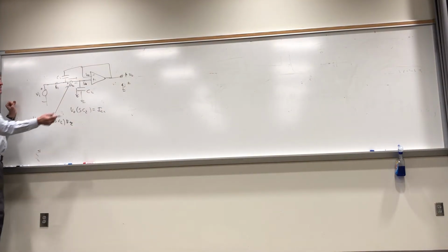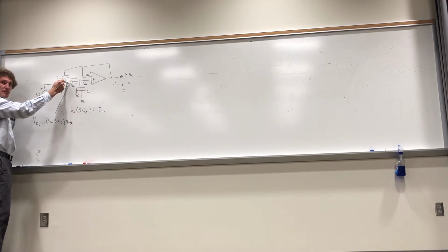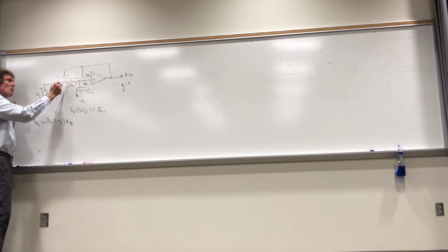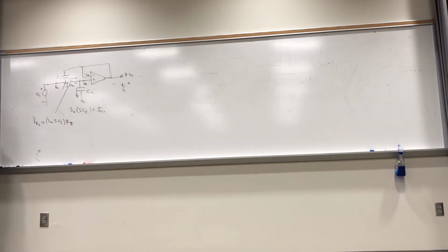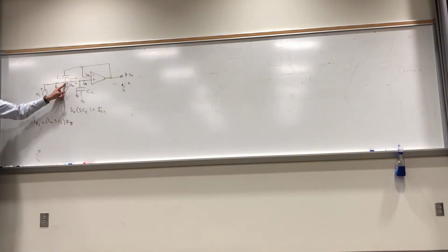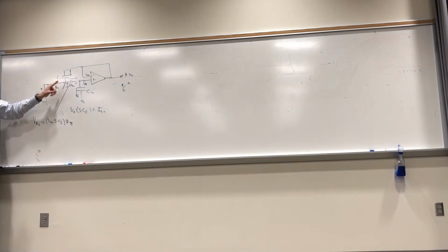Now, once you have that voltage as well as that current, right? You got that current right here. You got that voltage. Don't you have the voltage here? What is that voltage? It's going to be V naught plus this voltage, correct, class? Do you see what I'm doing? How many do? Please. If I have the voltage here, and I know what the voltage here is, then the voltage here is this plus this, correct? Once I have this voltage, don't I have the current flowing through here? It would be V naught minus this voltage times C1S, wouldn't it? How many see that? Right?